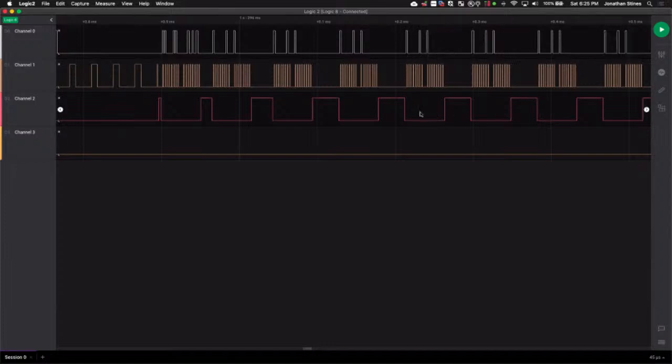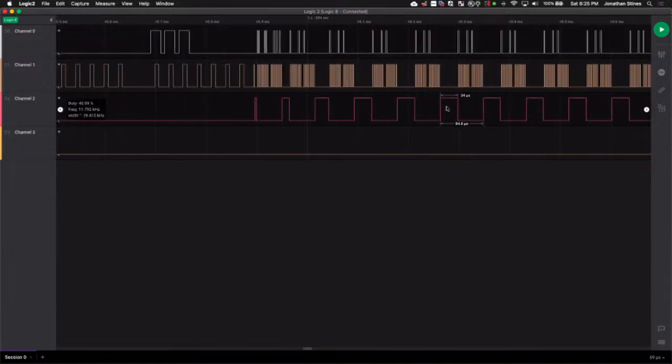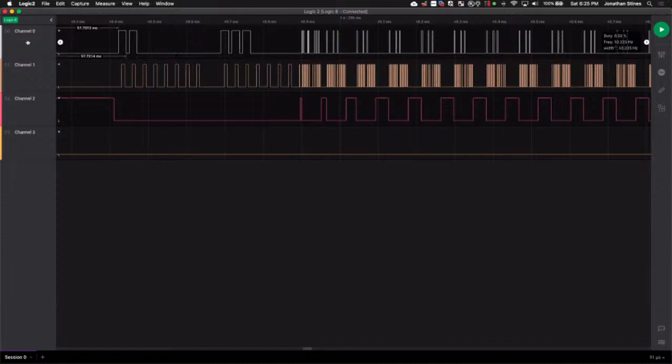It's going to encompass that entire section, if that makes sense, or cycle. So it's pretty easy to tell if you just scan it as we just did, which one's MOSI, which one's clock, and which one's going to be enable. Again, channels 2 and 3 are actually not even required.